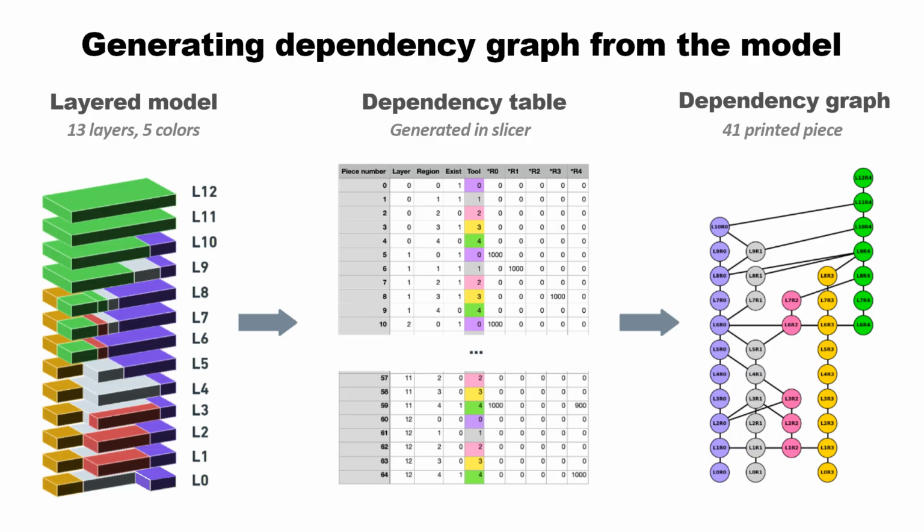In Prusa Slicer, for every color region, we can extract information such as its X and Y location, Z height, its area and perimeter. And most importantly, we can also calculate the intersection with other regions below. This will give us information about whether the color region can be 3D printed in a given layer, or whether we should finish printing the color regions on a layer below, before moving on to the upper layer.